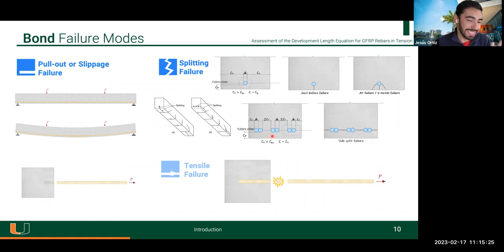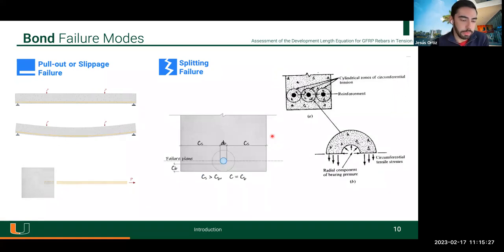If we focus on a steel rebar, that is maybe easier to see because of the ribs. In steel, this effect is called wedging action. That is when the pressure of the ribs against the concrete produces tensile forces, so the concrete starts to crack. If these cracks extend to the full bar length, you are going to have horizontal cracks and you are going to lose that concrete cover. If you lose that concrete cover, you are not able to transfer those stresses to the concrete and vice versa, so you are going to lose the capacity of your beam. So this is another type of failure.